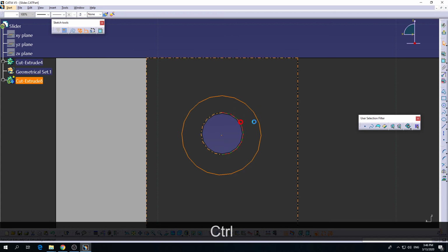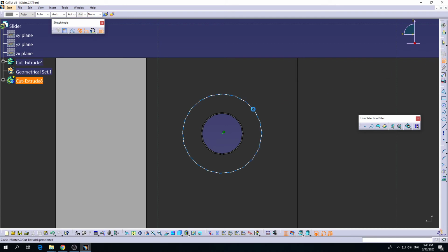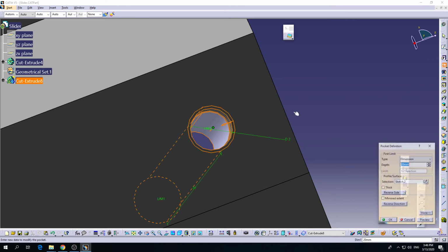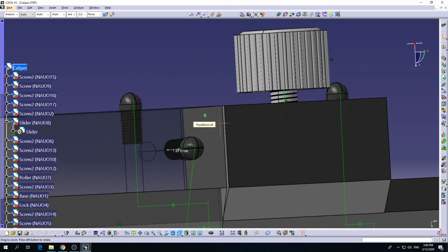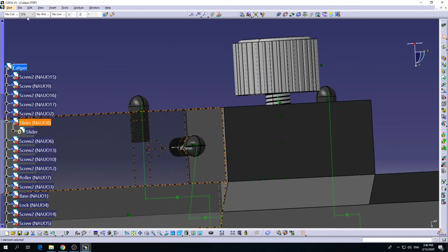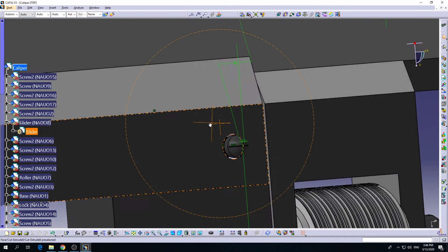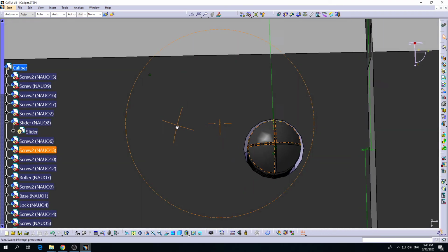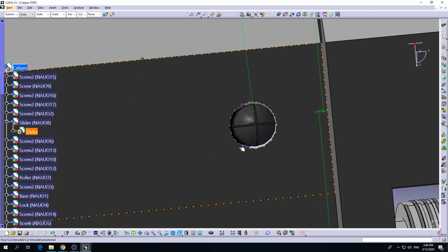I will just do a roughly large cut, let's say 2 millimeters. I will pocket that, and I will go back to the caliper. It should be updated now, so I want this to go again like that. Okay, so yeah, this is the issue. I did all the cutting and the analysis for that one while I adjusted the model on this part. So now I can see that there shouldn't be any clashes over here.